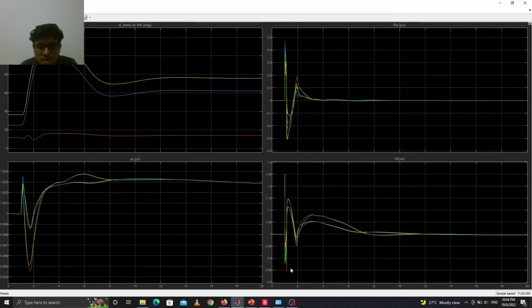The last one is the voltage magnitude versus time graph, which shows that the voltage waveform begins to become marginally unstable at the starting point at 1 second time. After that, the voltage magnitude suddenly becomes unstable again between 1.5 seconds until 2 seconds. Then the graph finally was stable at the 12 second and above.